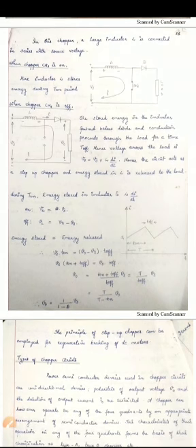So what is the total voltage across the load during this period, V0? At that time V0 is equal to Vs plus L into di by dt. You can see V0 is always greater than Vs because the energy stored in the inductor is also released to the load. Hence we can say this circuit acts as a step up chopper, where the output voltage is greater than the input voltage.